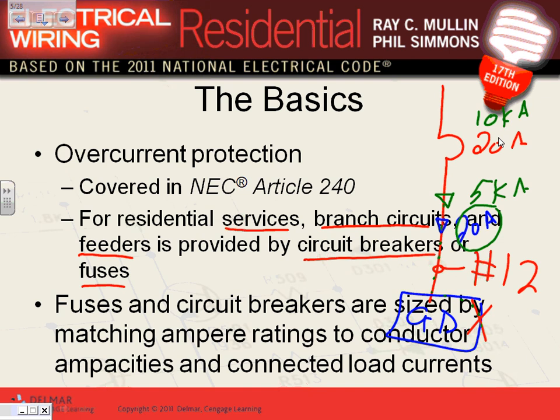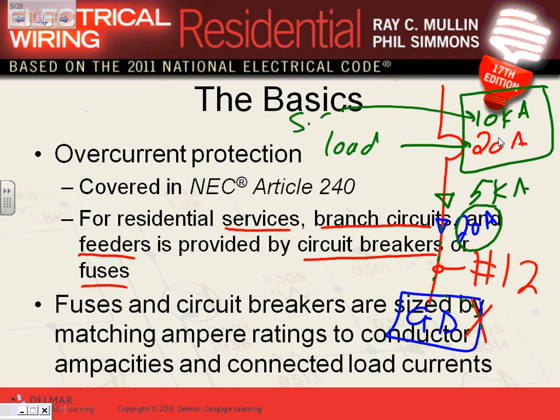Any question, guys, about this? Any question? So we have an overcurrent protection device. The most important thing, Oladipo, is this. We have an overcurrent protection device that protects from overload. This is this from load and short circuit or ground fault. So here's your load, and this value is for what? For short circuit and ground fault, for faults. So every circuit breaker has 2 values. One to protect you from short circuit and ground faults, the other value to protect you from overload.